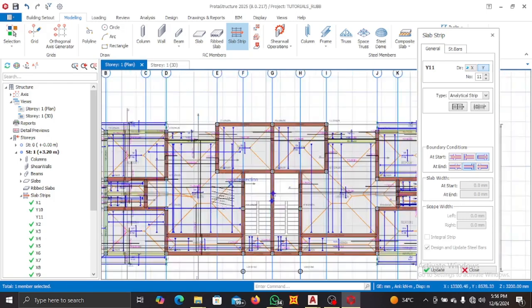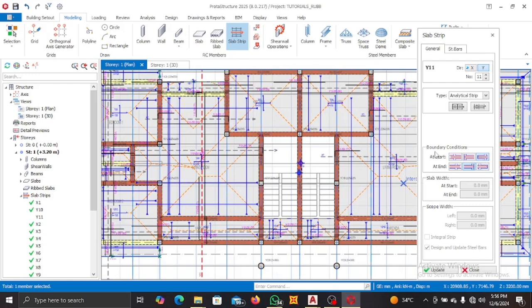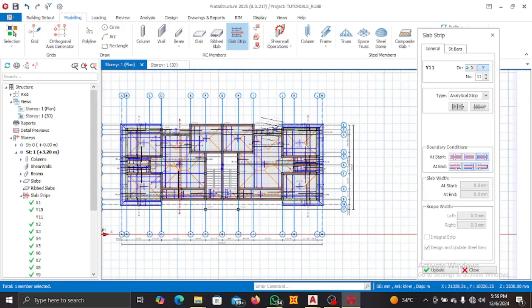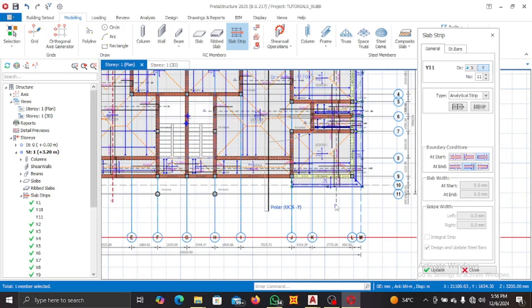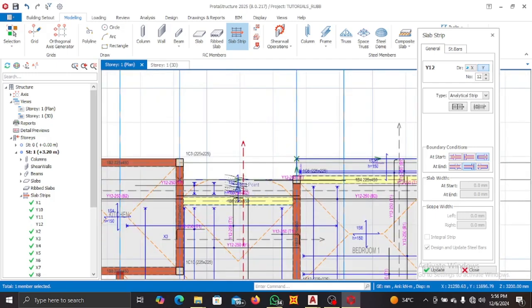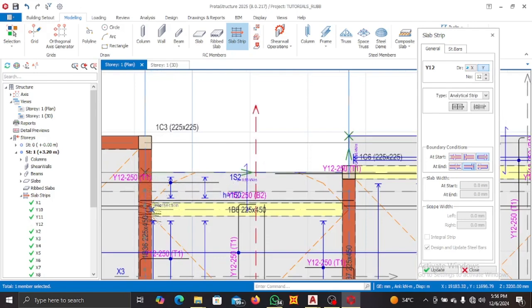Okay, that is for a cantilever, because literally that place is not a cantilever slab, so that's why it's acting that way. Here it's not a cantilever slab; it's supported on one side, two sides, and three sides, supported on three sides. To pass, you can leave it as a cantilever, but that's not a cantilever slab.